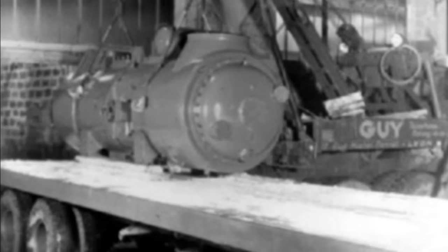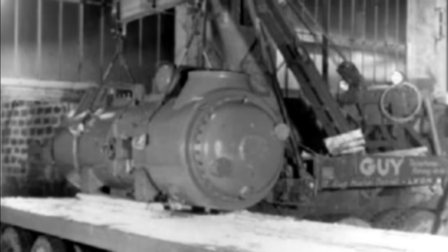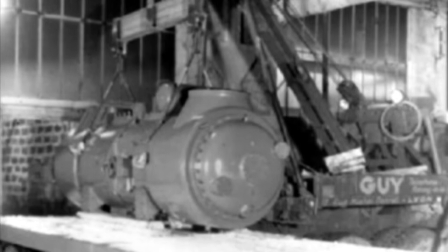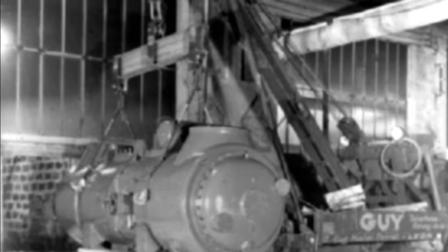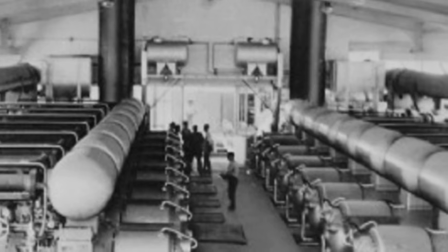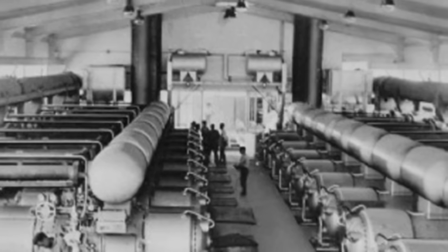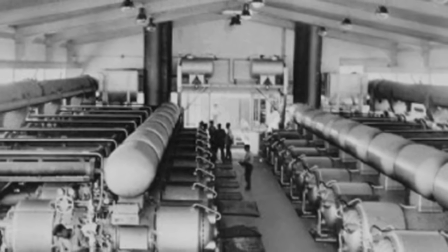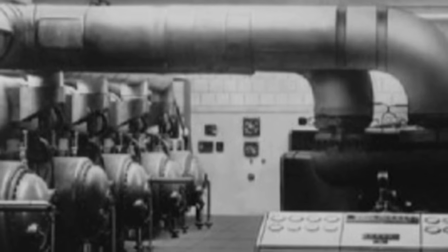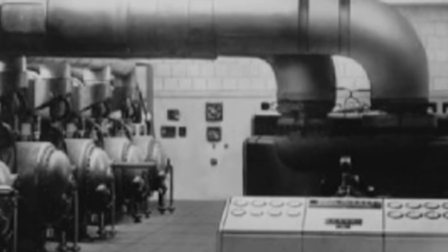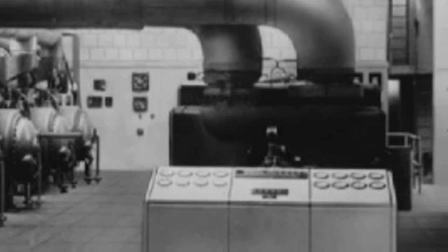The free-piston engine has a number of unique features. Some give it potential advantages, and some represent challenges that needed to be overcome. Since the piston's movement between endpoints is not mechanically constrained by a crank mechanism, the free-piston engine has the valuable property of variable compression ratio. This variable compression ratio allowed the use of different fuels with different auto-ignition temperatures. It performed well on high-octane gasoline, diesel fuel, kerosene, shale oil, butane, and even peanut and other vegetable oils.